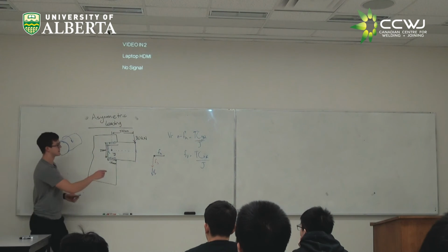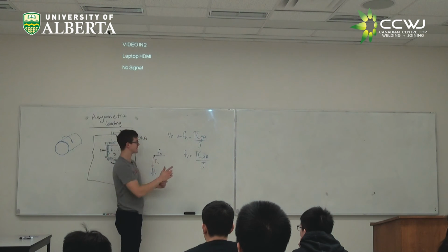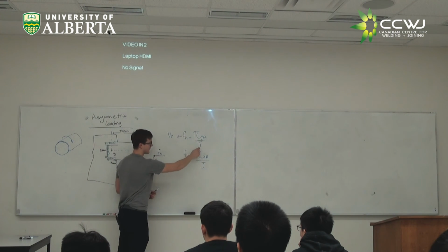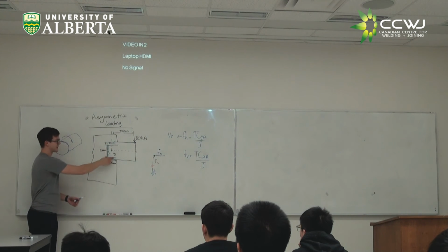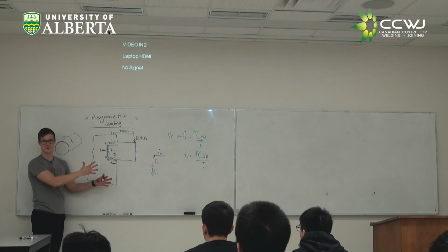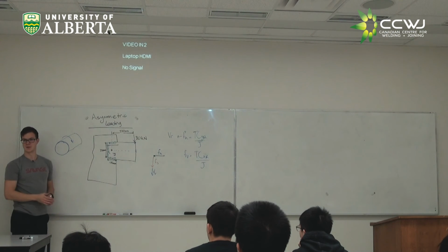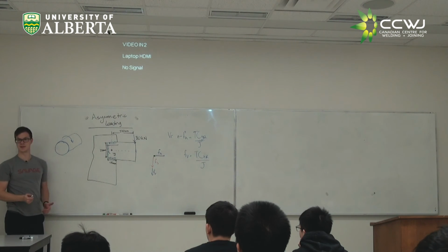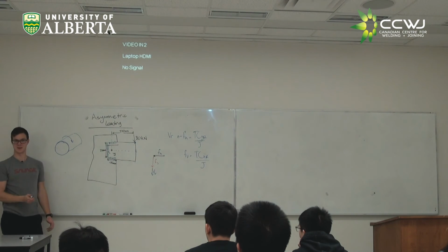So what we end up doing is calculating a radius, the c or r, for our cylinder, the torque we're transmitting, and this J is calculated using the properties of our section. Because it's not a circle, the formula for J is not as simple as if it was a cylinder, but we're given those formulas in the class notes, and you'll be given them on the exam. And then functionally doing the exact same thing you did here. Does that make a little bit more sense, maybe?